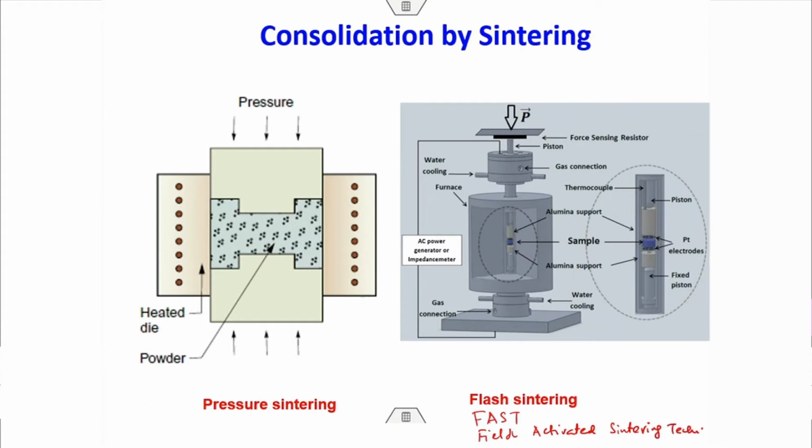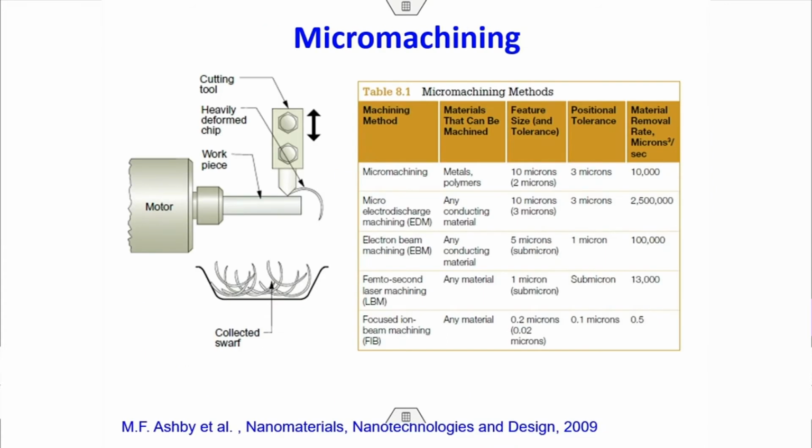Right, that's what is widely used. Well, then you can do micro machining, which can lead to a lot of chip formation, and because of machining, shear force is pretty high. So therefore, this leads to a lot of nanocrystallization in these chips, and the chips can be ground and made into powder, and the powder can be consolidated. Okay, so there are many machining routes.